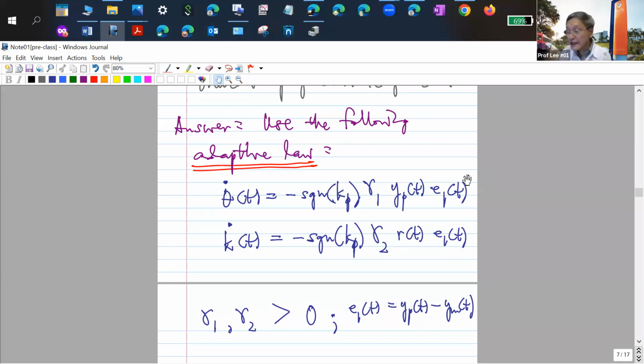And if you want to be very careful, particularly for the 8 PhD students, if you need to do your work very carefully with this kind of system, first of all, you need to show that your system obeys a Lipschitz condition, that there is no finite escape. Because linear systems, even if unstable, will go unstable at most in an exponential fashion. It cannot go faster than that. When you have an exponentially unstable system, at any point that you look at it, there's still a signal. The signal may be large, but there's still a signal.